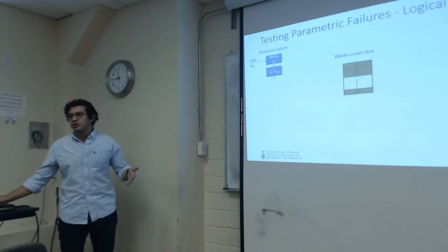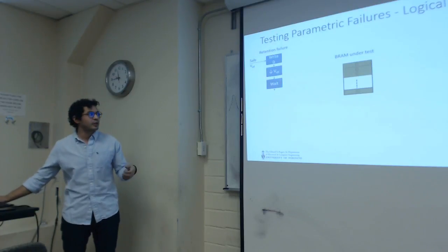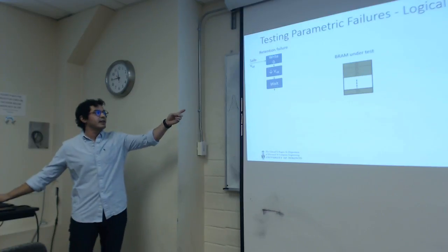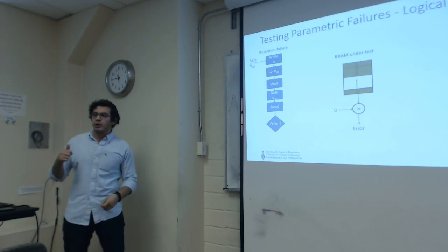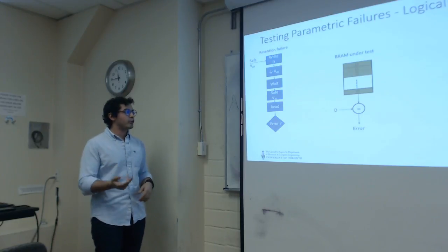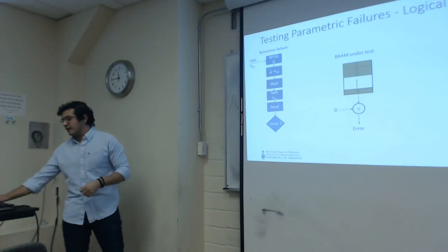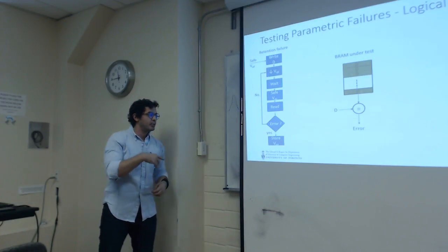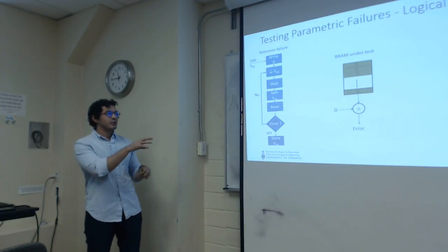Then we reduce the supply voltage and wait for some time to make sure that the chip is able to retain the data stored at this supply voltage. And then we increase the supply voltage back to a safe value, and we perform a read. If we read the same value that we've written, then that's good. We can go back and reduce the supply voltage and repeat this step until we find the minimum voltage that can maintain the value stored in the SRAM cell.